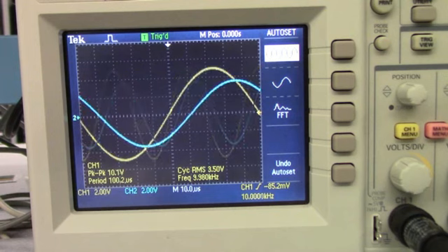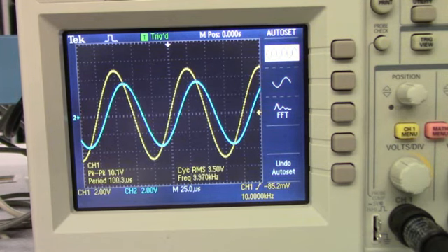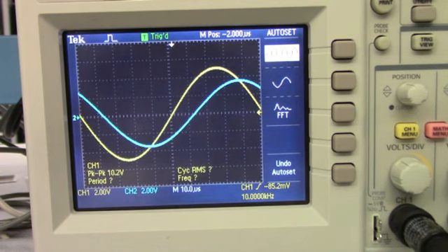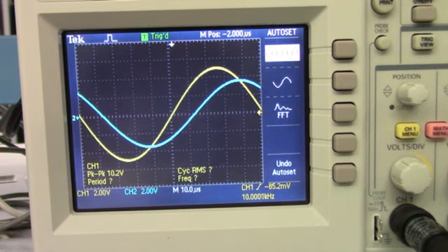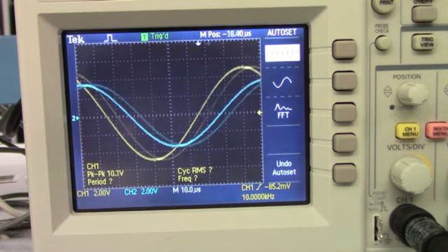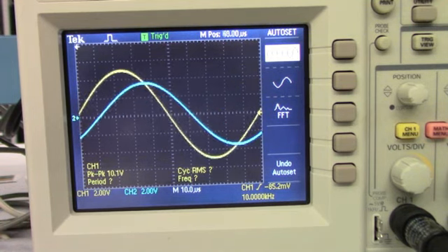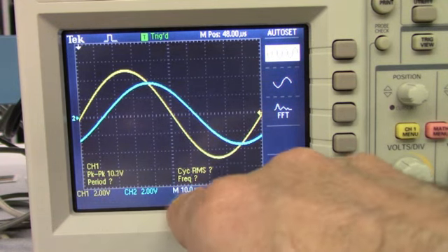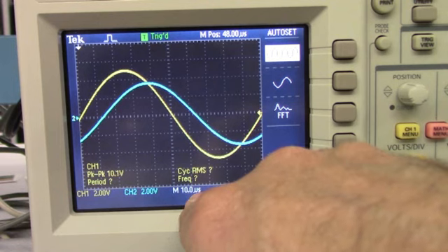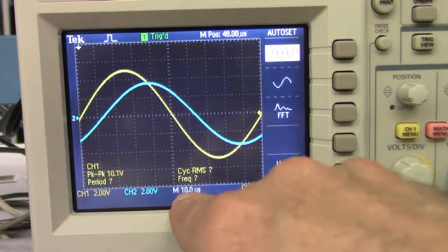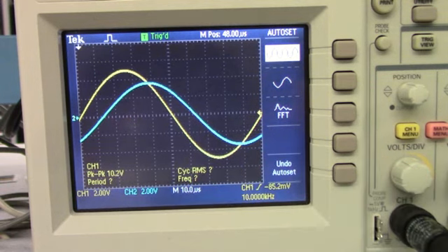And we want to zoom in. Once again, we don't care what's going on with 5 of the same thing. And now we can see that there's a phase shift. And if we measure that phase shift, it's pretty close to a full cycle. So this is 10 microseconds per division, 10 divisions, 100 microseconds, because we have a 10 kilohertz input. And we'll notice that we've got 1 and about 1/2 division, which is 15 microseconds of phase shift.